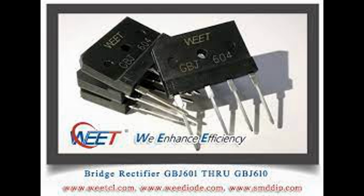The rectified DC output from the bridge rectifier is fed into charging circuits, which control the charging process to ensure optimal battery health and longevity. Float charging. Once the backup batteries are fully charged, the battery backup system may switch to float charging mode. In this mode, the bridge rectifier continues to supply a trickle charge to the batteries to maintain their charge level and keep them ready for use in case of a power outage.